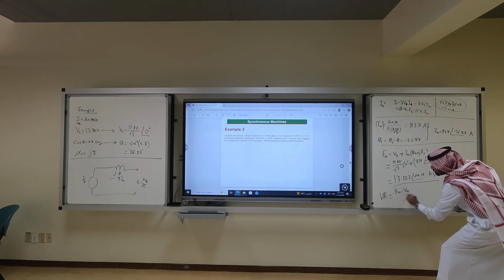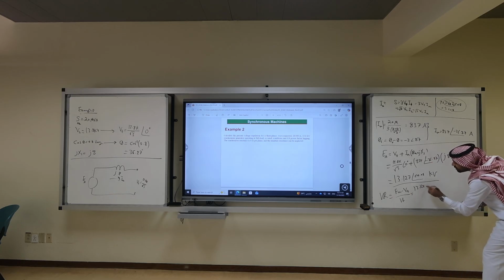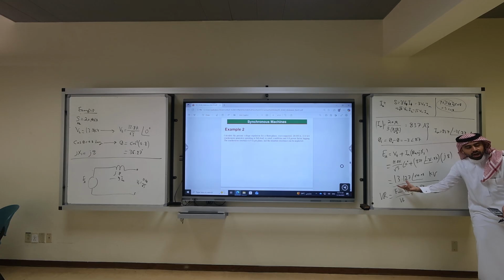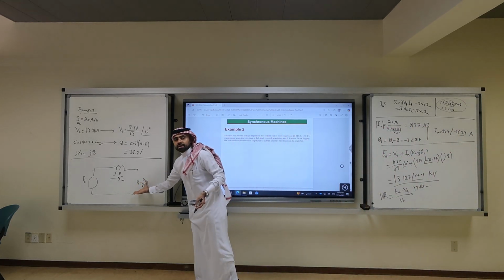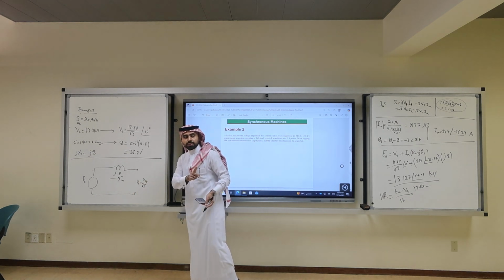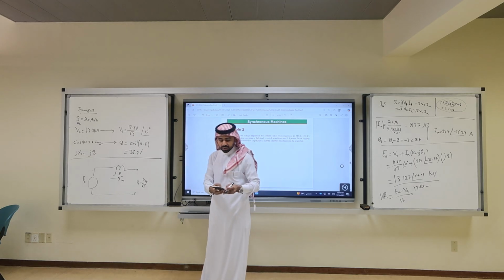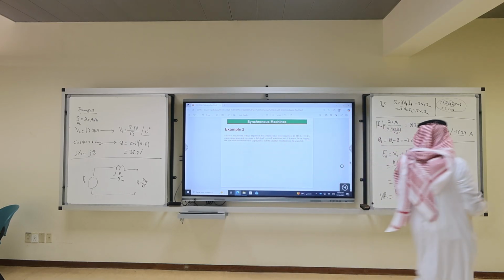EA minus VT over VT percent. 13.127 minus, what is VT? Wrong. It is not 13.8. It is V terminal, which is a phase quantity. Is this a line to line? No, it is from a single phase equivalent circuit. This is a trap. So you subtract 13.8 divided by square root of 3, which is